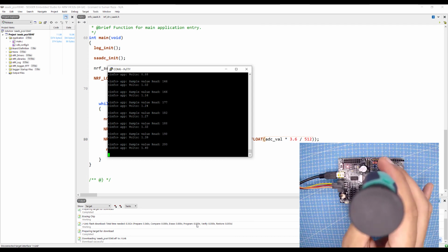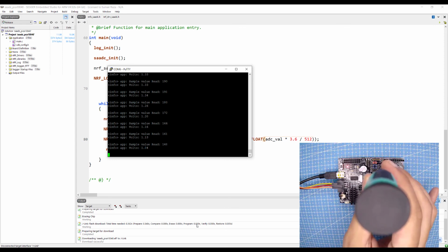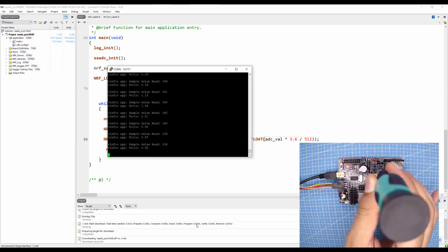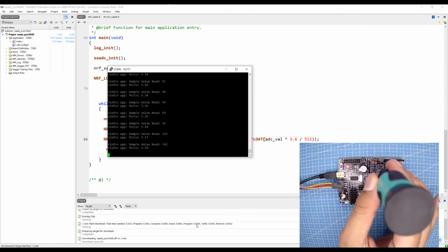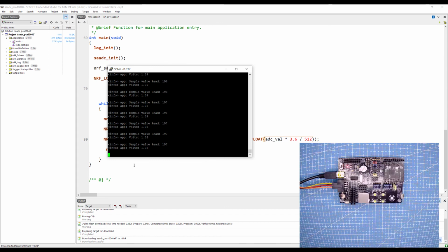So basically with the differential, there is a little difference between them. If you're interested in working with the differential ADC, you can check it out. Single-ended is recommended for beginners, and if you are already good with ADCs, just go with the differentials, because they give you some other stuff as well. For more information, you can check out the differential inputs for the ADCs and so on.